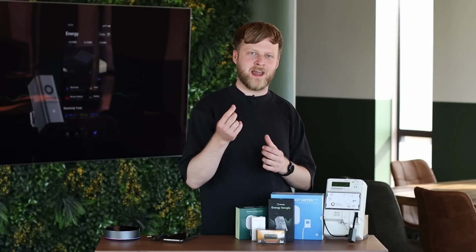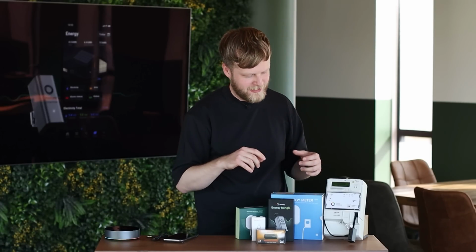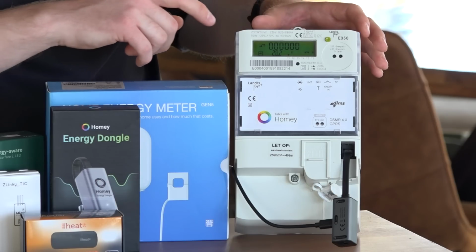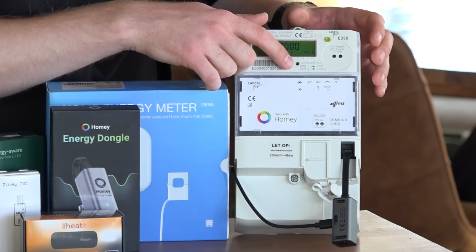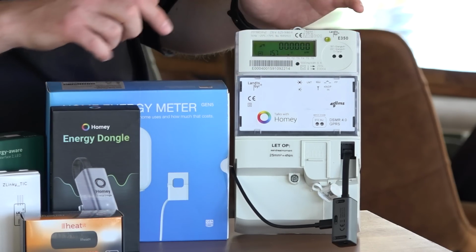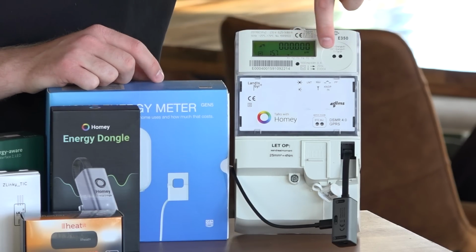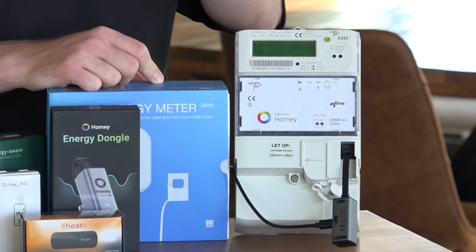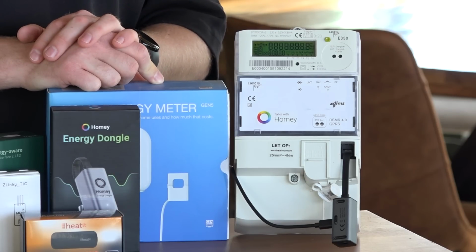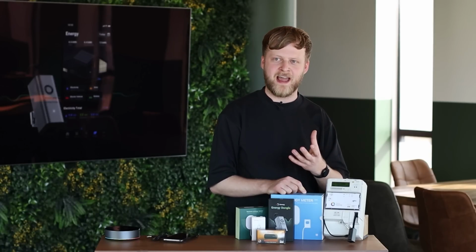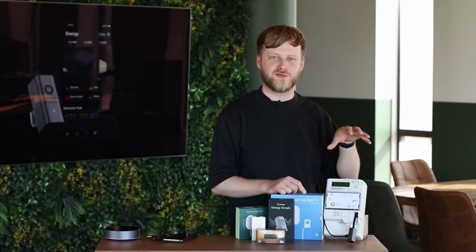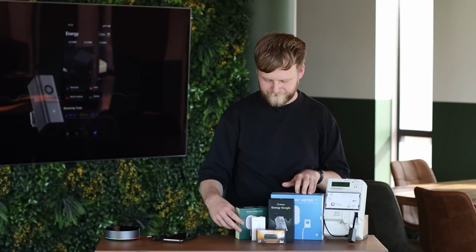One standard that almost every digital meter supports uses a very clever trick, actually. If we look at the energy meter here, we can see a small blinking LED at the front. That LED is blinking, in this case about 1,000 blinks per kilowatt hour used. And we can use that LED to get the energy usage from the digital energy meter.